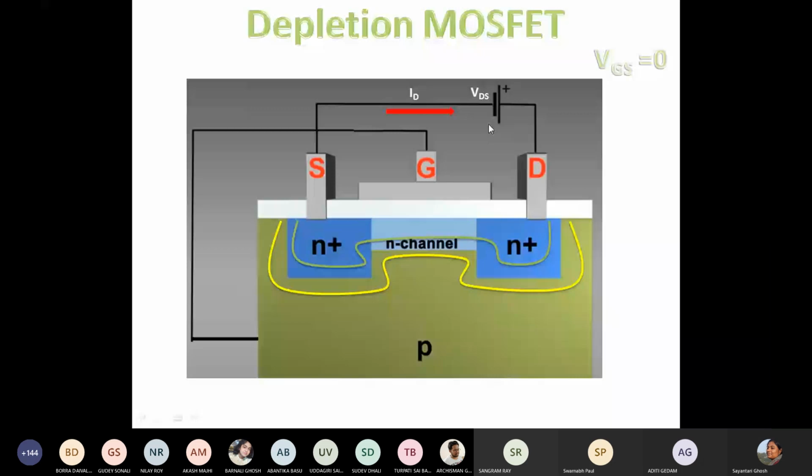though the current flow tries to increase, some opposing force also gets developed, because the depletion region gets broader and broader as more and more reverse bias is applied across this p-n junction. This p-type side is the substrate, and via the source it is connected to the same battery. The p-type side is connected to the negative side of the battery, while the n-type side is connected to the positive side of the battery, applying a reverse bias.